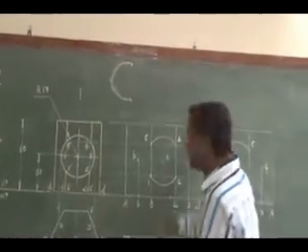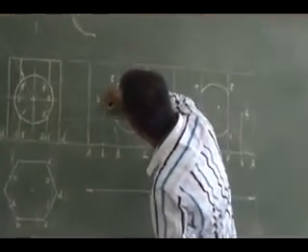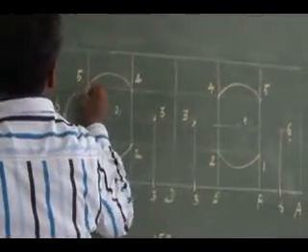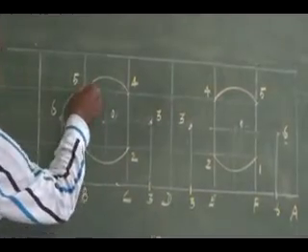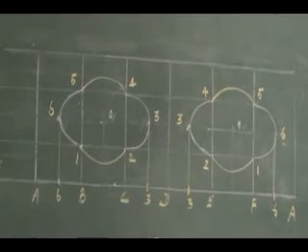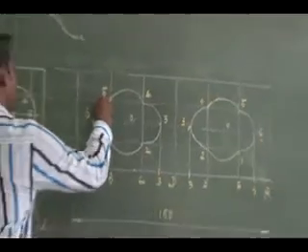Just smoothly connect with a 3-point arc like this. This development, if I fold it, I will have a exactly circular hole seen in my front view. I will keep this solid. Okay. So this is the way you have to draw a 3-point arc.